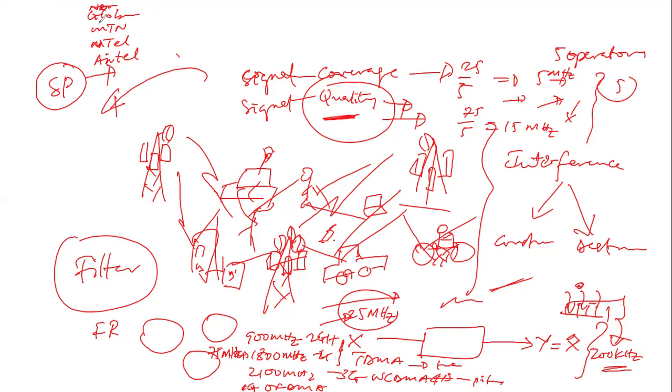So it means that each of them has 5 megahertz. Now, out of these 5 megahertz, the channel size or spacing is 200 kilohertz. That's 5,000 kilohertz, divided by 200 kilohertz. So how many 200 kilohertz channels can we get from here? That's about 25, right?